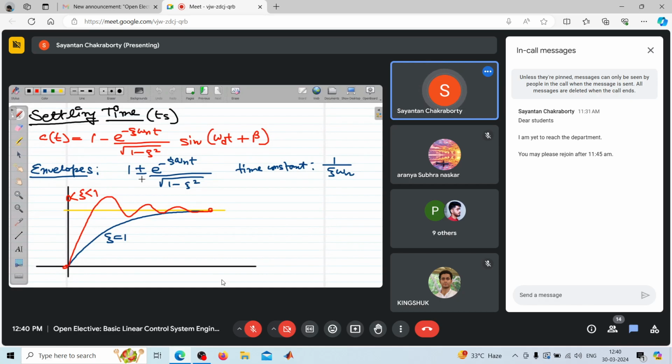We set a value of damping at 1.1 or 1.2, so that even under the uncertainty or parameter variation, there is a margin of 0.1 or 0.2 of damping. After that, it will become underdamped. So even under the uncertainties or the parameter variation, it will still remain at least critically damped. There's a factor of safety remaining there. Okay, so that's a very typical situation. Normally, that is how we deal with control problems because we cannot be absolute about such parameters. There are many reasons.